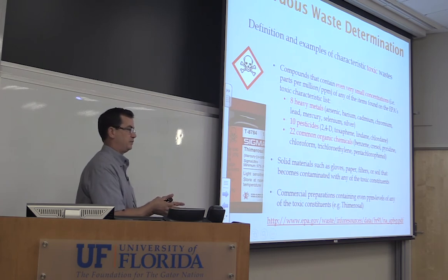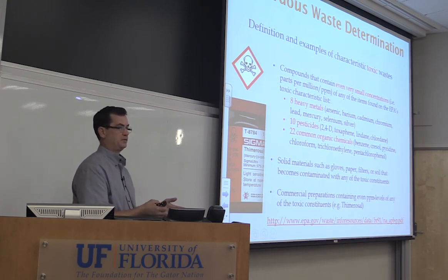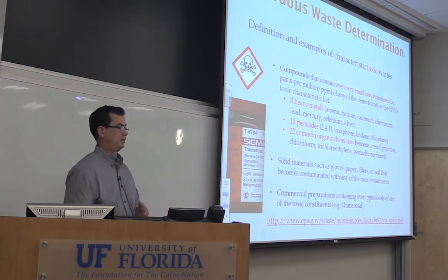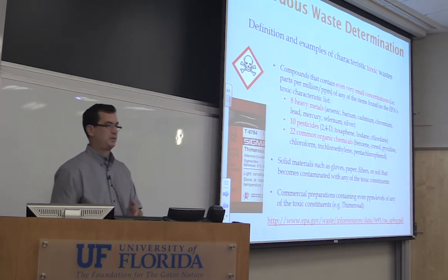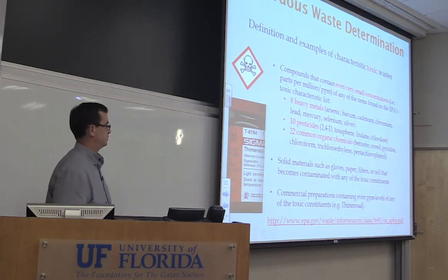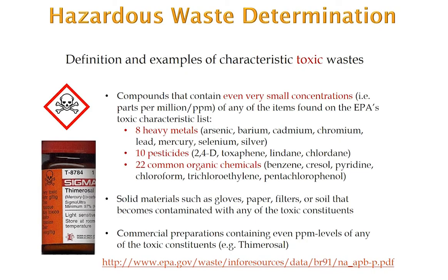At that level, you're almost always going to meet the standard. Parts per million is 1/10,000th of 1%. So if you're working in percents, you're well over that threshold. So if it's in your original starting material, it's going to be considered a hazardous waste because of that characteristic of toxicity. Knowing your product, once again, I'm repeating myself, but know your products.